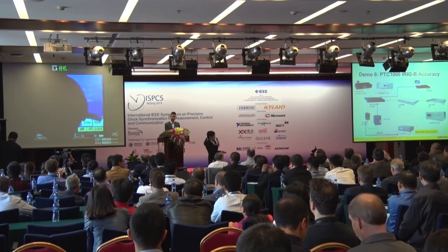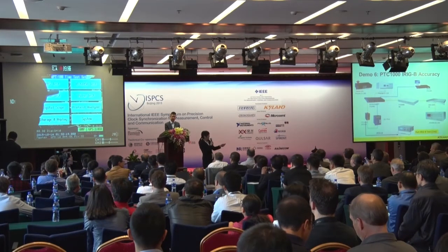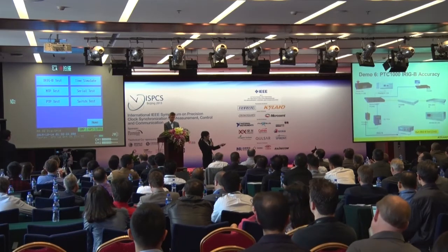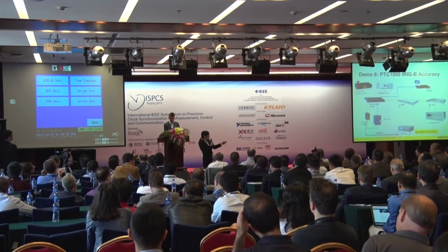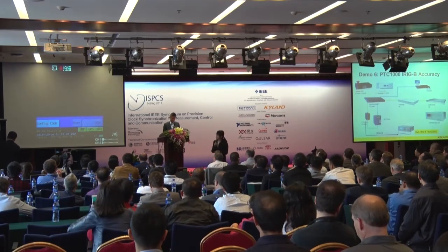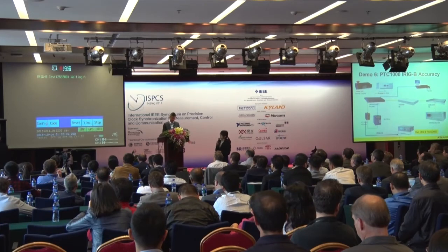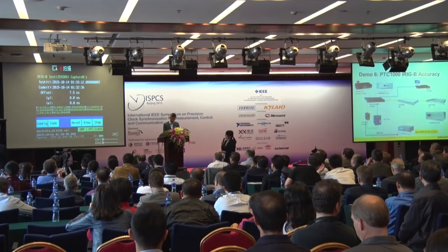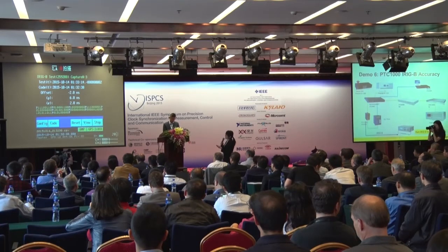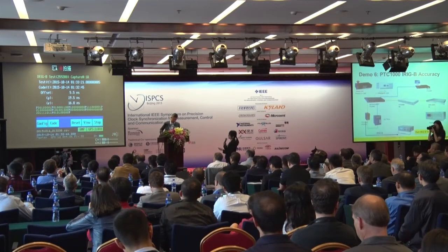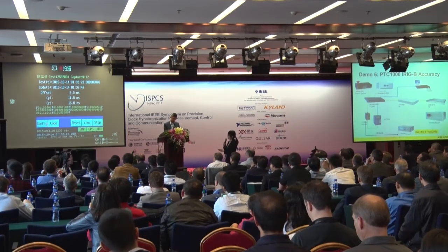Since we are using a clock converter, we can also use the time tester to check the output of the IRIG-B from the clock converter. Now we start the IRIG-B test here. And from the screen, we can not only check the time offset of the IRIG-B, but also all the decoded information of the IRIG-B.